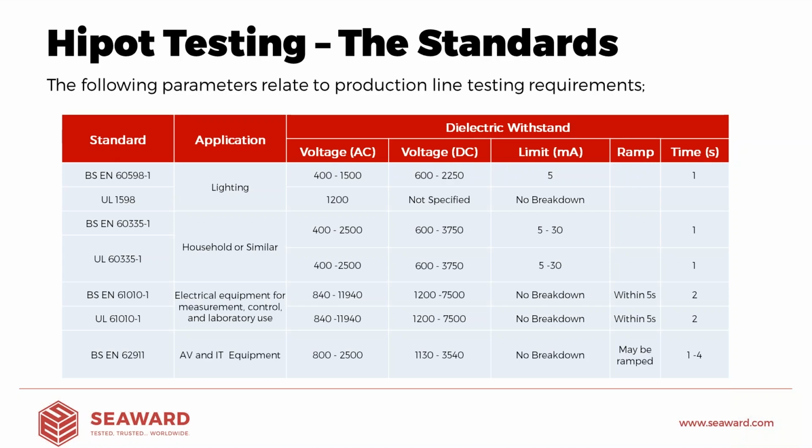So we're just going to finish this up now with a quick poll, and then we're going to have a couple of video demonstrations to show you, showing some breakdown, showing a flashover condition, and also the difference between the readings that you may get on an AC and a DC test on exactly the same product. And that will show the total leakage measurement, including the reactive element, versus a true leakage measurement.